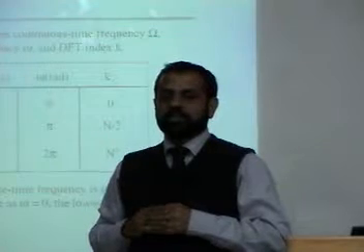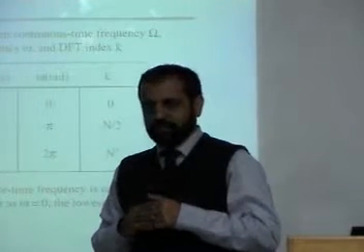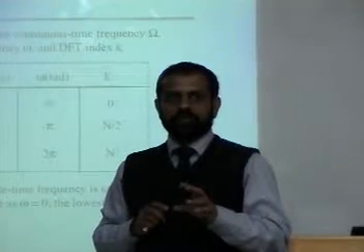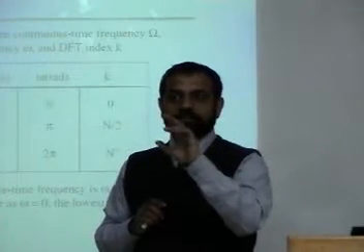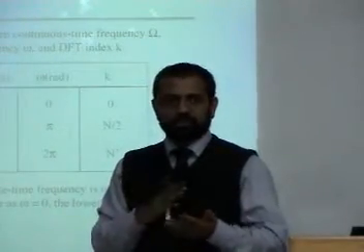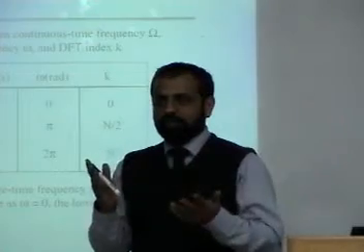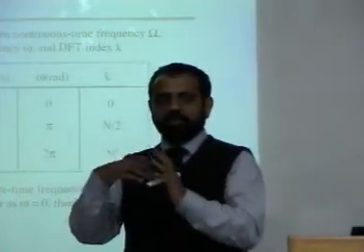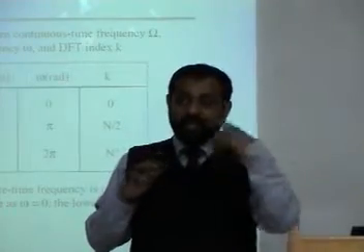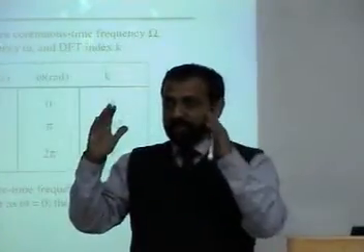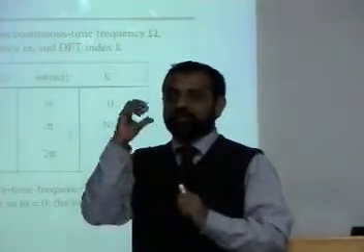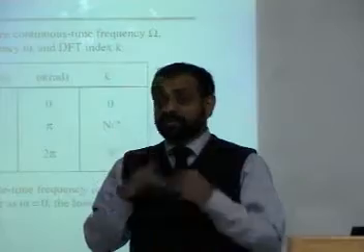Yes, I am saying it, basically it's an abuse of the term, so to say. The bandwidth is an abused term. Okay, the bandwidth of a link you say, but it is in some form related to the actual bandwidth of the channel. Now, in information coding you should learn the channel capacity theorem: if you have this much bandwidth, it can only support this much data rate with the signal to noise ratio. So though it is indirectly linked, the bandwidth is the band of frequencies in which you can transmit. Data rate is related to that.